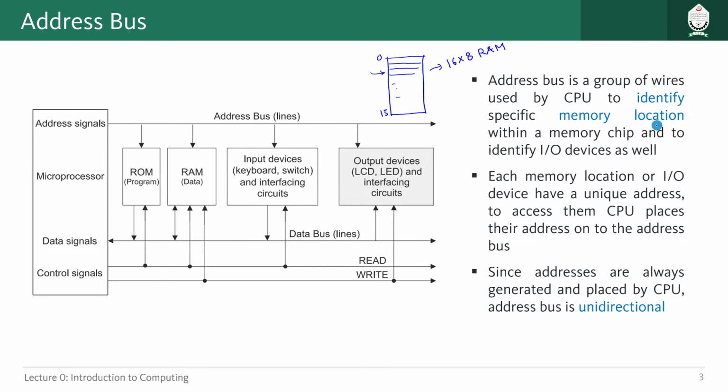So we are calling it a memory location, basically that is what memory location means, and each of the memory locations can have a different amount of memory. Like for the case of SAP 1, that was 8 bit. So in total we had 16 different lines or rows, each of them had 8 bits of data, right? So the address bus here basically will try to locate those.